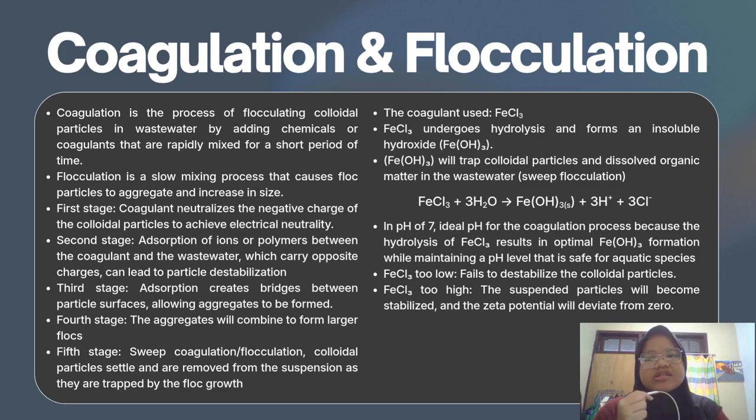After the secondary stage, we move into the next stage, which is the tertiary wastewater treatment. Tertiary wastewater treatment is an advanced purification phase designed to remove the pollutants that are resistant to both primary physical processes and secondary biological degradation. The aim of this stage is the removal of stable colloids, nutrients, and heavy metal residue to achieve solid removal efficiency approaching 100% and BOD reduction up to 99%.